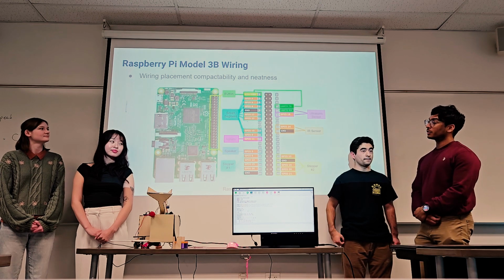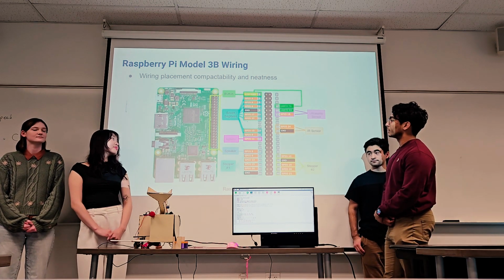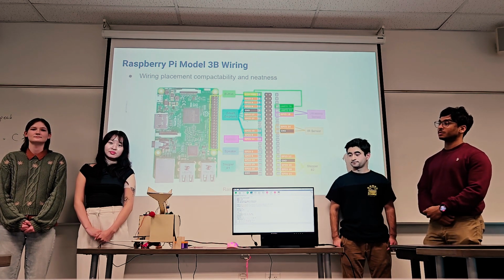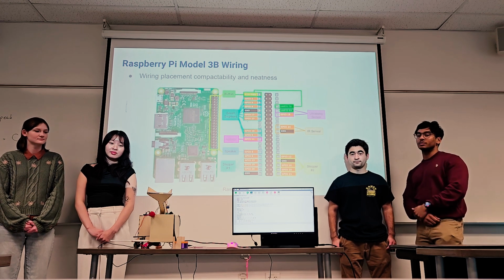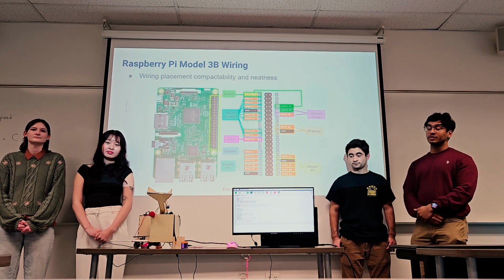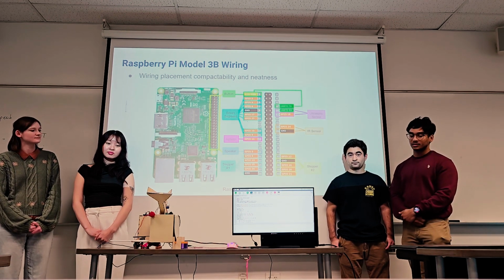So for our wiring on the Raspberry Pi, we used up most of the GPIO pins that are available. So we have a button, we have the 7 segment, we have space for an agitator to help shake the funnel, but we ended up not needing it. We have a speaker, we have the 2 stepper motors, and we also have the 2 sensors, the ultrasonic sensor and the infrared sensor.